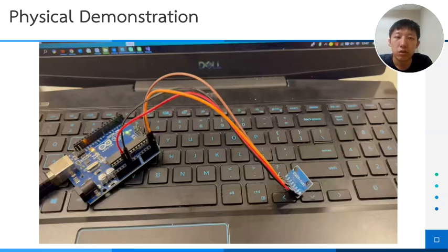Before the physical demonstration, I will first explain the final effect and knowledge points. The summary of knowledge points. First, cross-language communication: C# and Arduino C++ realize data interaction through serial communication. The key is to ensure consistent parameters such as baud rate and a clear data format agreement, such as comma separation. Second, hardware communication: the MPU6050 communicates with Arduino through the I2C bus and can complete data transmission with only 2 wires. Accurate wiring is the premise of successful communication.